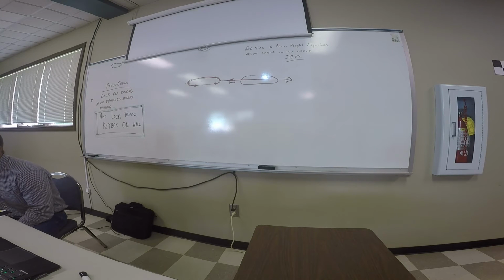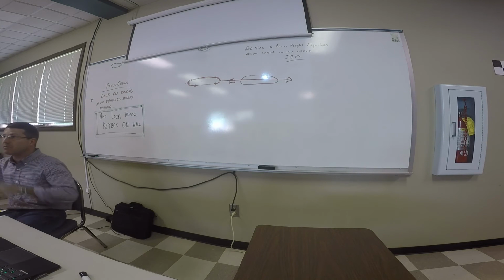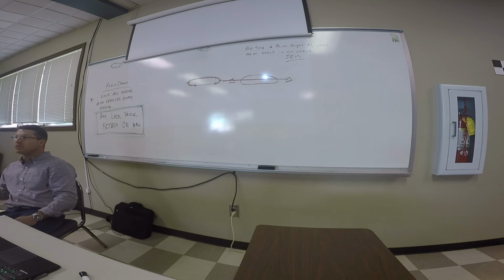So, finish floor, building heights, top steps. When y'all shoot something that's a top step, that goes on a layer in our field to finish. It goes to our finished floor layer within the CAD file, and we freeze that layer so top steps disappear. We use those specifically for drafting, not for elevation.